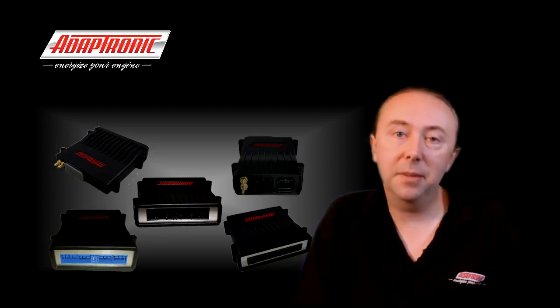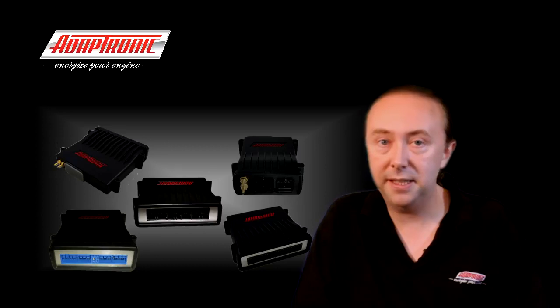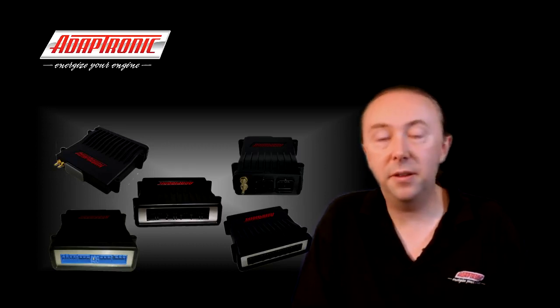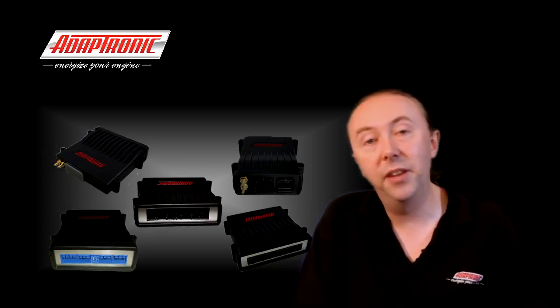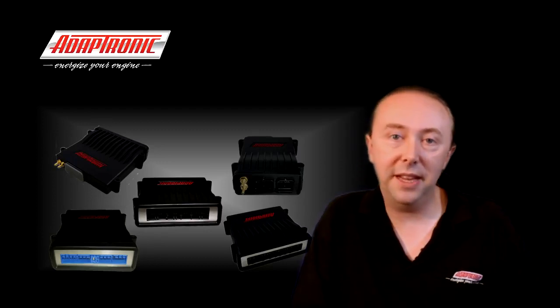So for the sake of an example, let's say that we want to use those 2 RPM points with 100 RPM hysteresis. So this means that as the RPM increases from idle, the valve will turn on at 2000 RPM. The RPM will need to go below 1900 RPM to switch off again. If you keep accelerating, when the RPM gets to 5000, and then it would need to drop to 4900 to turn back on again.